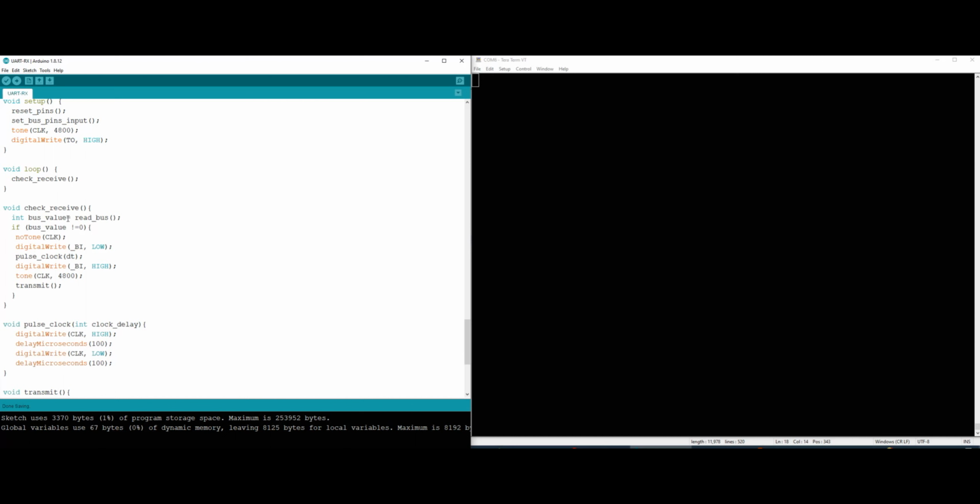However, as I said, we have to stop the clock at the moment we see the data on the bus, and then read that value into our B register. If you remember from the module for the A and B register, to read data into our B register, the only thing we need to do is bring the BI line, or let's say underline BI line, low, because this is an active low pin, and then pause the clock, right?